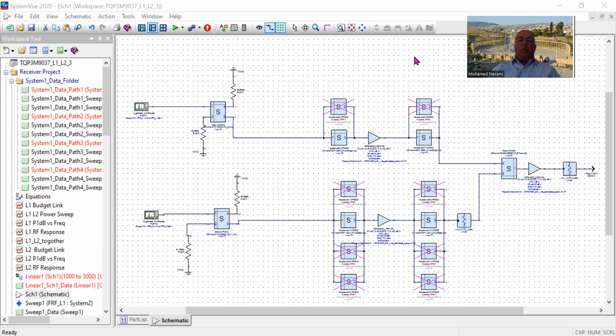And then we had another session on a complete transceiver front end for L band Iridium, which uses a 10-watt GaN device for a PA. You can refer back to my videos on those.